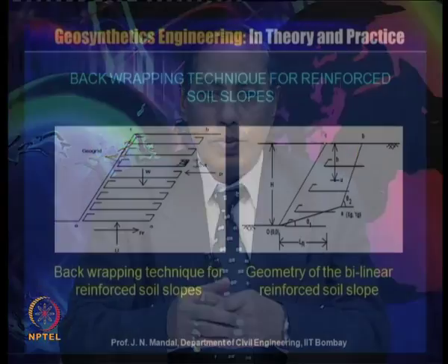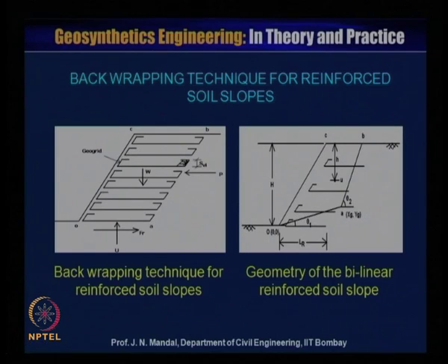Now I will focus on the back wrapping technique for reinforced soil slope. So this kind of technique is particularly suitable for the slope where space is restrained. You cannot place the reinforcement up to a certain length.